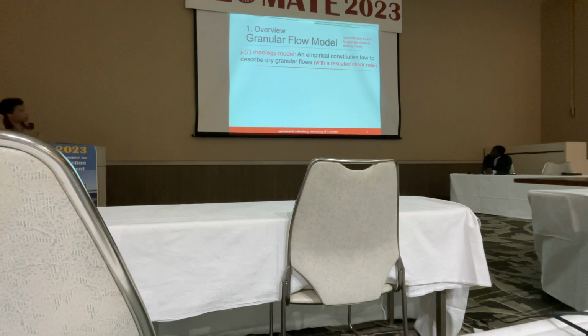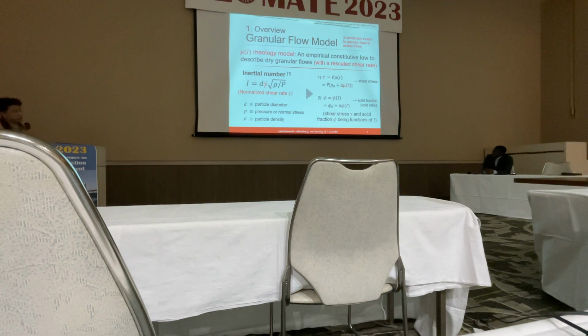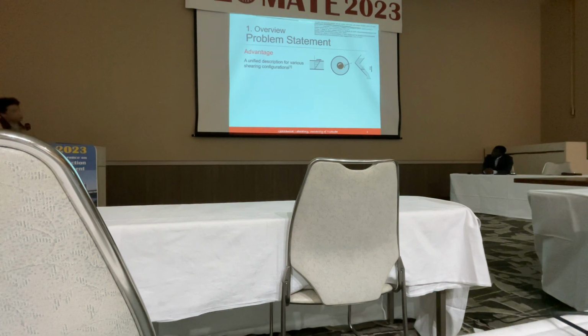Recently, there was a very popular model called the rheology model, which is used to describe the rheological behaviors of granular flows. In this model, the researchers introduced the rescaled shear rate called the inertia number to describe two key parameters, the shear stress and the solid fraction, or the void ratio, of the granular flows, which is proven to be valid for different geometries. However, you might notice that this inertia number contains very limited information on particle properties.